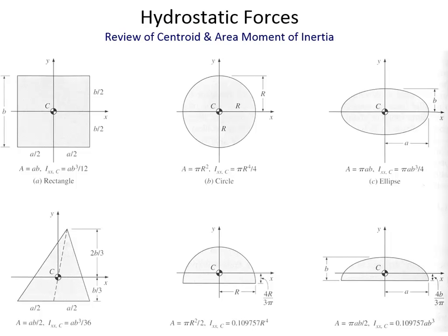All right. Well, we're going to talk about hydrostatic forces on flat surfaces today, and one of the important things that we have to do when calculating the location of hydrostatic forces is consider the area moment of inertia of a shape. And at the back of your book are a couple of formulas for area moment of inertia, if you don't remember them from statics when you had these sorts of things. But almost exclusively what we'll be calculating is the area moment of inertia around the x-axis. Most commonly it'll be for a rectangle.